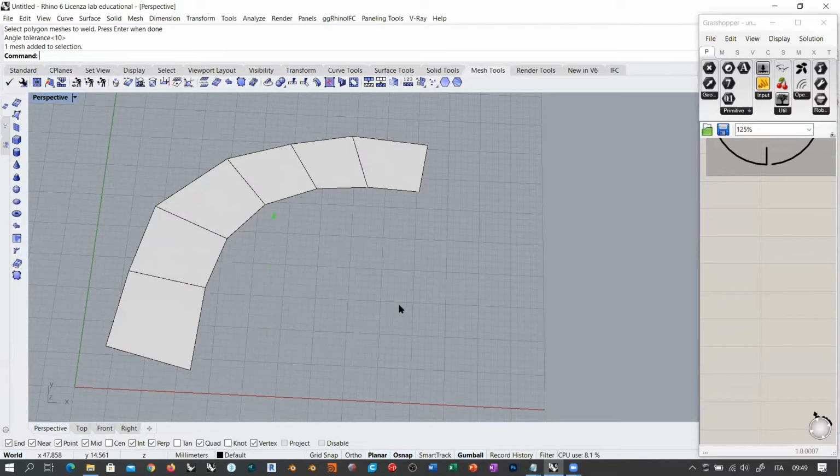What's the meaning of this? When you create a mesh with two edges and faces, and I'm going to exaggerate here, as if they were separated, this line from this line, but they are coincident, welding means this. These two vertices that lie one on top of each other are not actually blended into one single vertex.